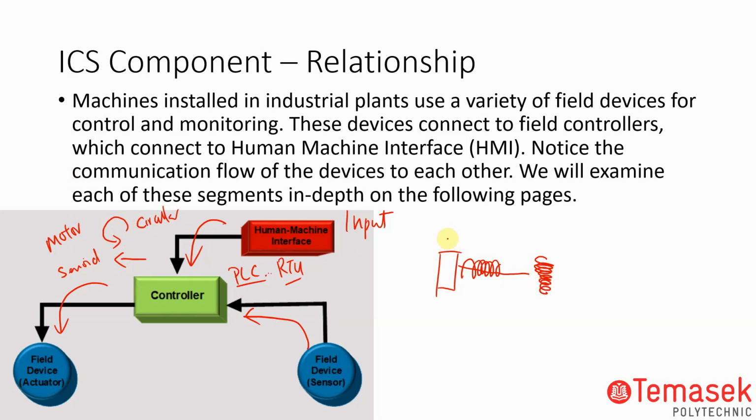This is a permanent magnet, this is an electromagnet. So you power on, it will pull this thing in this direction. If you release, the spring will force it back in this direction. That's why it's a solenoid. For example, you have a pump or cooling water or whatever, that is a solenoid at the end of the day.